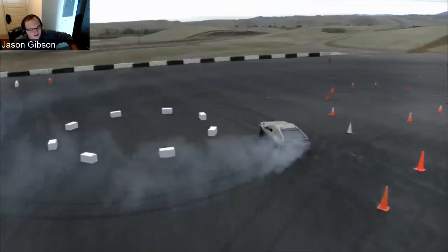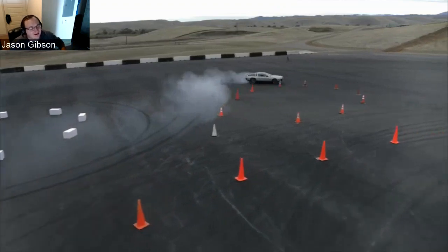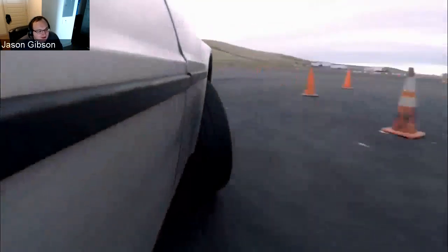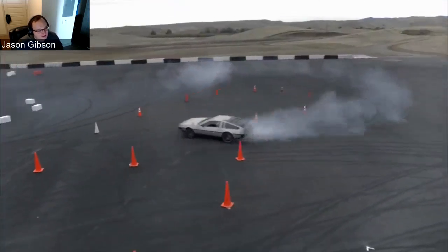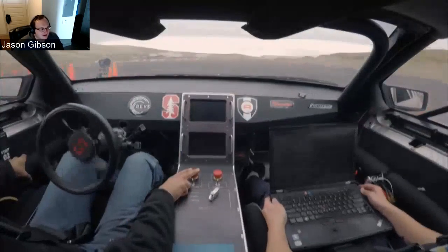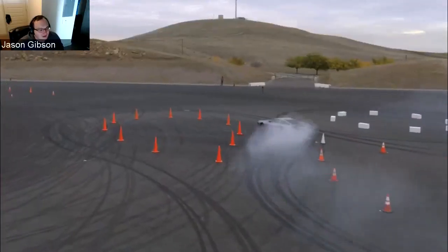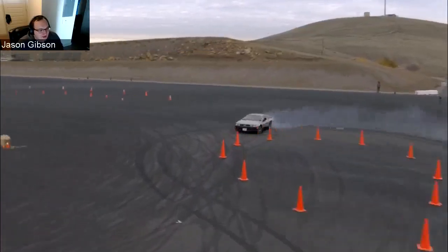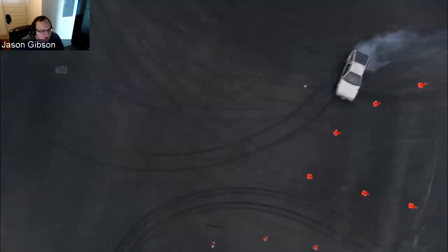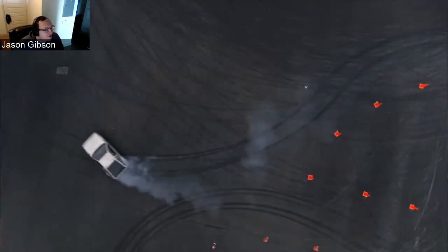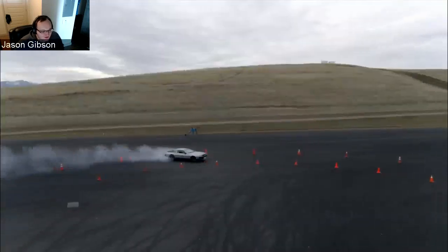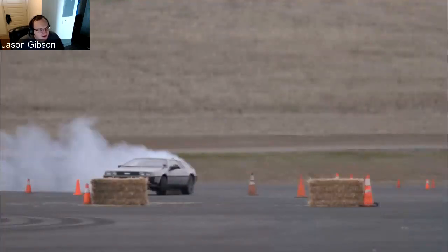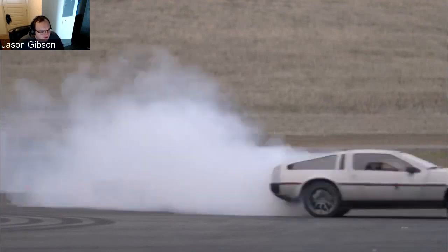So this is essentially just using pure pursuit and PID. They're using a little bit of adaptation online as it drives, so essentially it changes the PID constants as it drives. So it's a little bit more advanced, but fundamentally not that complicated. You guys could totally learn how to do this. It's mostly just the application of the thing that's the complicated part. And someone letting you do this to their car. So if you're ever like, wow, I'm not learning practical things, right here. All of these really basic algorithms can get combined into something really complicated and really interesting.